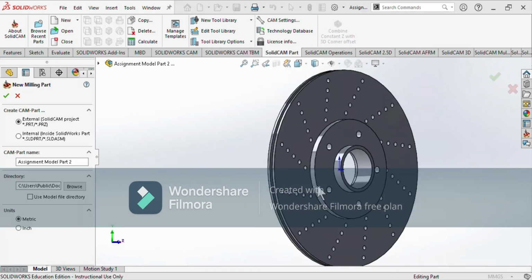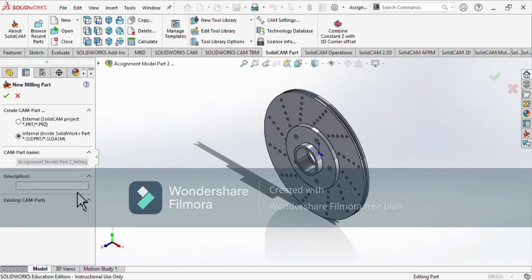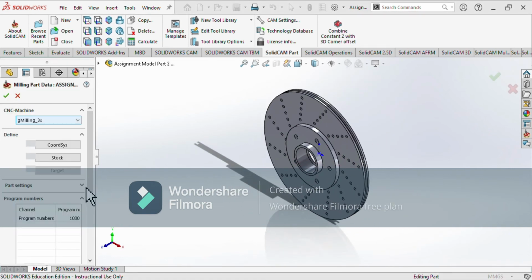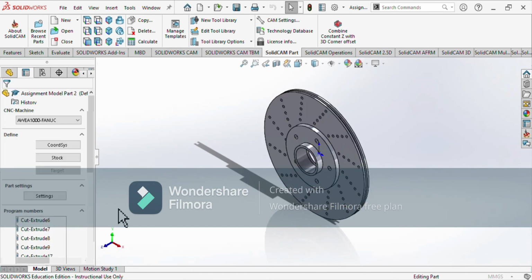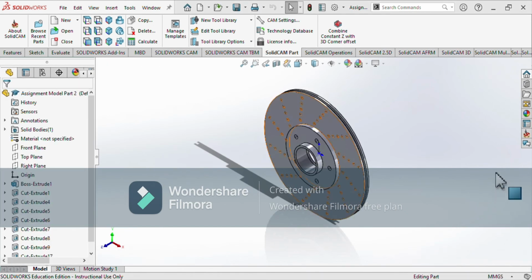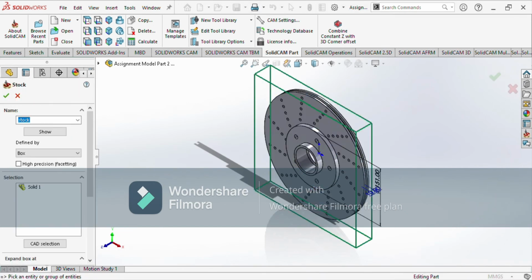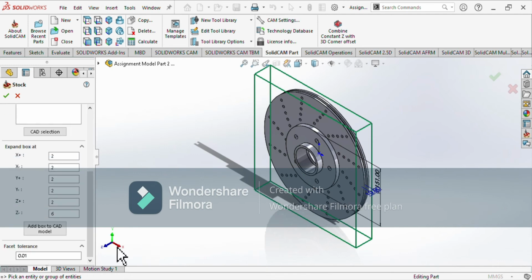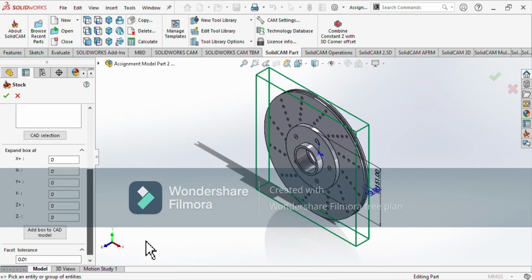Then we need to create a new milling operation for the back side of the brake disc. The clamping position is changed from being vices on the side to being clamped on the inner surface of the brake disc, which protrudes outwards. This will allow us to profile mill around the outside edge of the brake disc, as well as the T-slot,